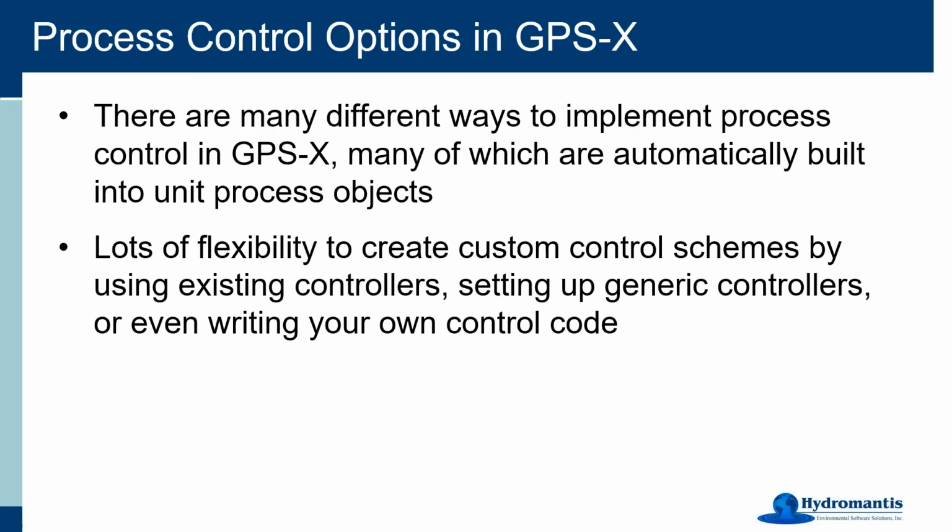just simply put a bit of control idea behind something, it might not necessarily be a full-on dynamic PID control loop, but maybe you would like to say something like, when the flow is above a certain level, I want to do flow splitting in a certain kind of way, and at a different level, I'm going to split the flow a different way. That kind of algorithm, do something different during the weekdays versus the weekends. Those things can be nicely written out in Axle code, and if you go to our model customization tutorial, you'll be able to see how to do that.